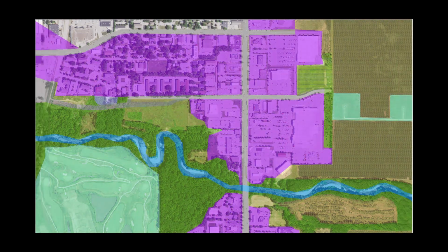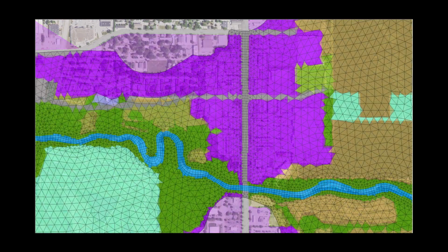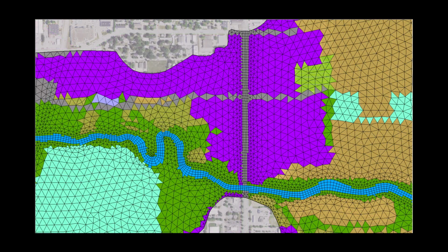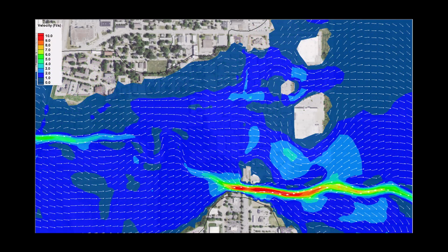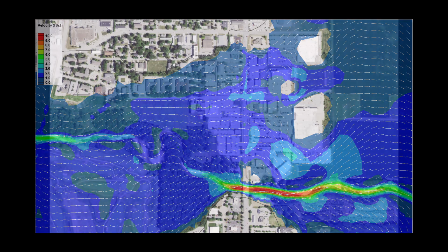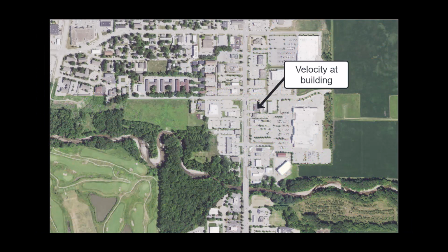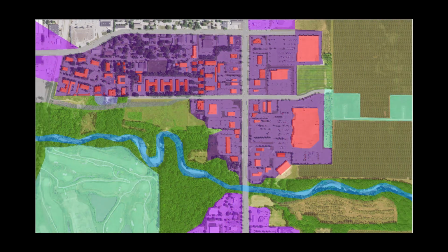This approach provides a simplified method to account for hydraulic roughness over a large area using a less refined mesh. This method does not capture flow variations along roads and around buildings. This approach is adequate to represent larger areas where detailed hydraulic results are not necessary. If more detailed hydraulics are required, or if the urban area is in close proximity to the project area of interest, a more detailed representation of the buildings may be warranted.